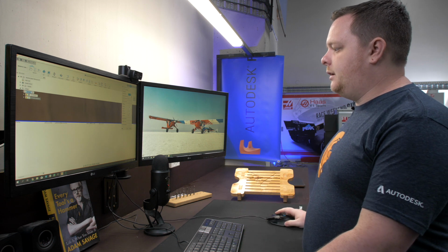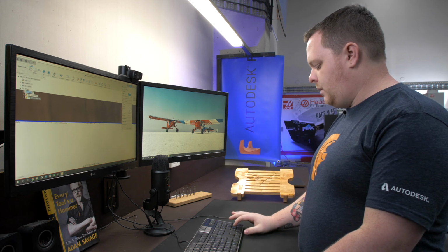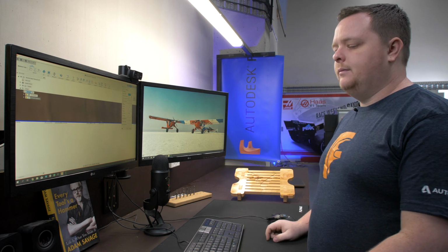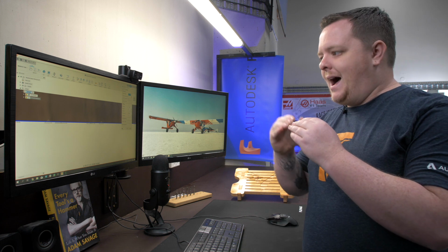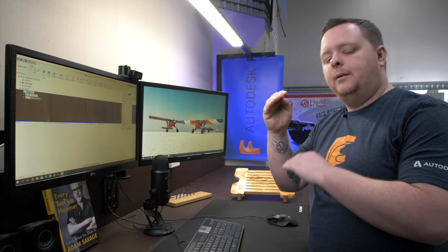So what I'm going to do is, well, I want my tab height to be 1.5 plus 1. And that's going to bring those tabs up another 1mm. There's still going to be a little remnants of a tab down inside the wasteboard or down a little bit lower, but the point here is to make sure that the tabs are actually holding the part in.